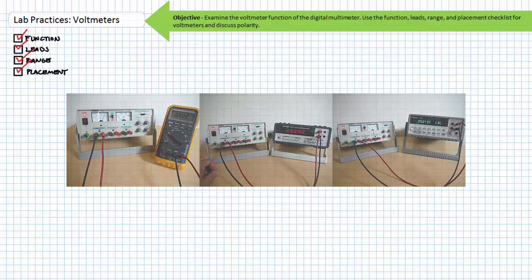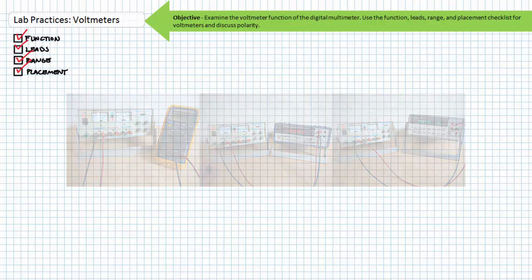Final note about these 3 different voltmeters: notice the small difference between readings we observe for the same voltage source. This voltage source is not a reference voltage source, meaning an official standard, nor are these voltmeters calibrated. We should expect to see variations in observations using different equipment. That being said, the voltmeters are in general agreement with each other, and I'd be reasonably confident this source is close enough to 5 volts.